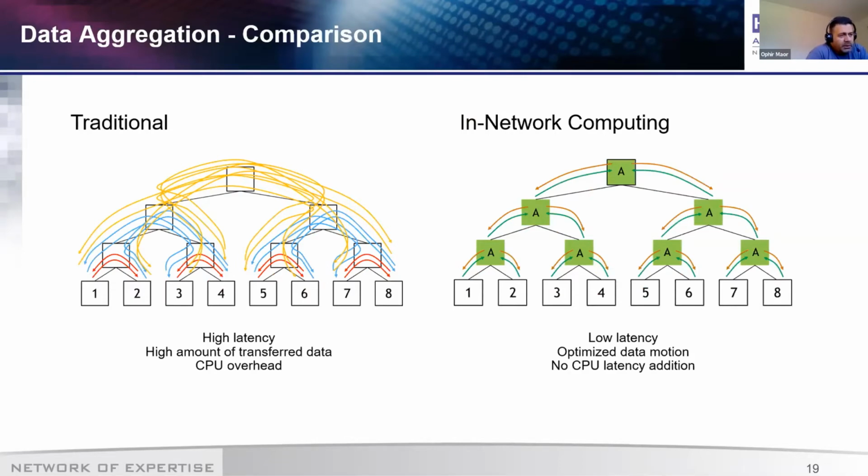When we are talking about collectives such as reduction collectives, such as all reduce, barrier, and all to all, for example, instead of just sending too many packets and waiting for all this latency, you can do that very, very fast with the switches. The switch does part of the performance, part of the collectives, on the switch memory.